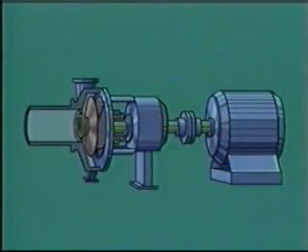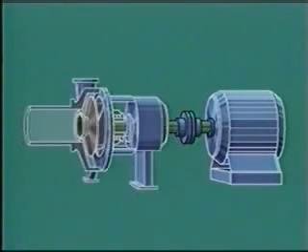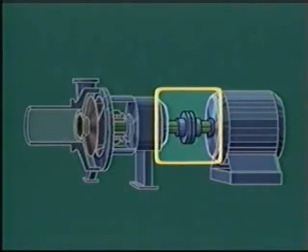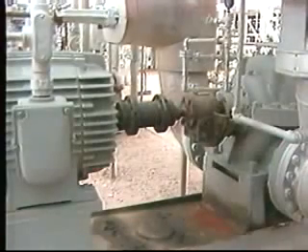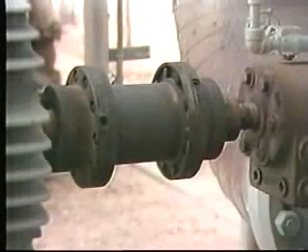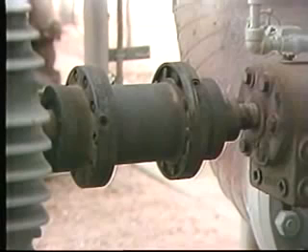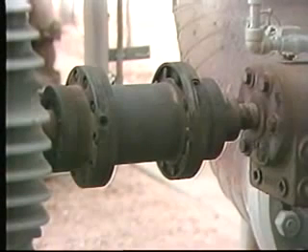Let's stop. Here's the driver. There's the pump itself. What links them? This, the coupling. It connects or couples the driver to the pump. And it does so for a purpose, to transmit power from the drive shaft to the pump shaft. Although they might seem simple, couplings are as critical as all the other components. They've got to be strong enough to withstand sudden changes in the pump's load and also those times when the driver might stop.